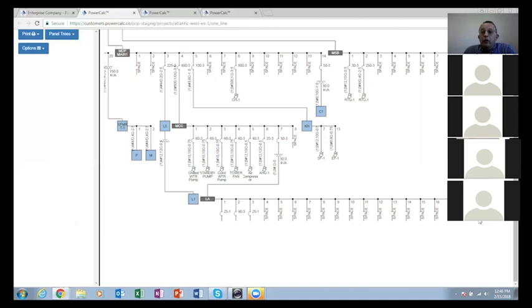Also, it gives you the most economic, cost-effective design. There is no over design, there is no under design, there are no over values or under values. This is exactly what the NEC is telling you to do. So engineering wise, it does its own calculations based on the engineering and the power requirement as electrical engineering. And then it goes and matches your calculations, the amperage, the overcurrent protection device, and the conductor size with the NEC. So it gives you the most economical design that you can obtain.